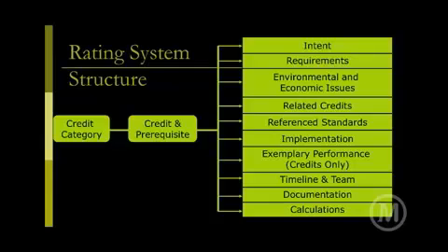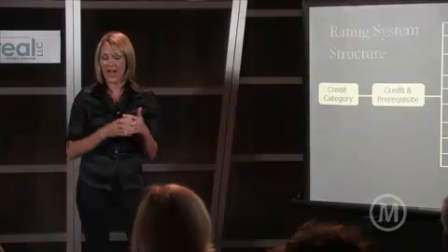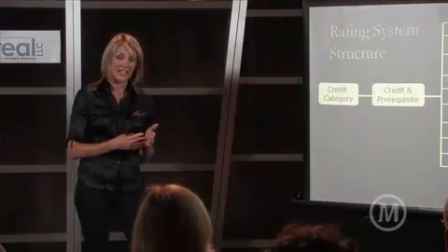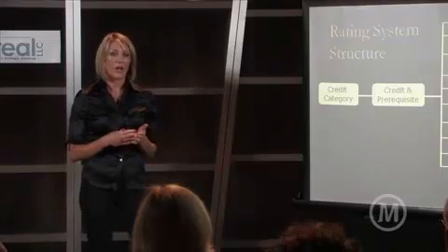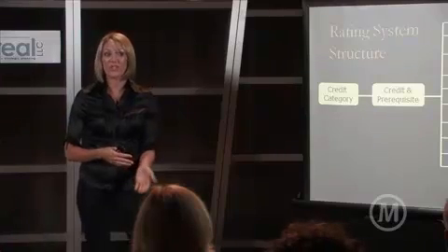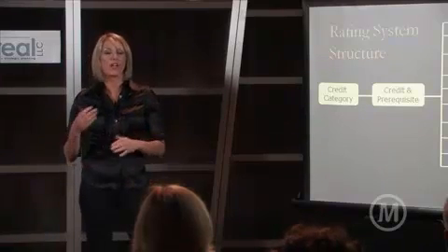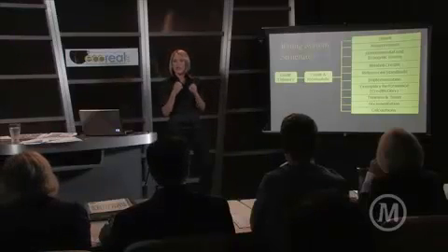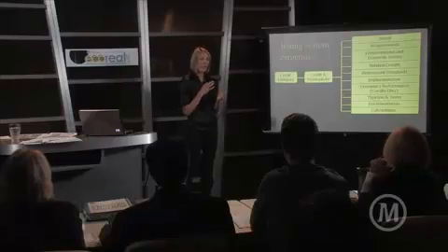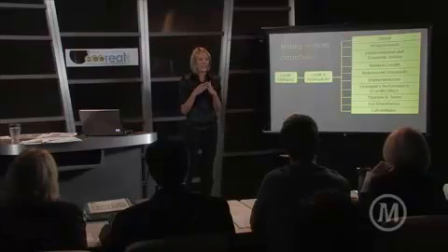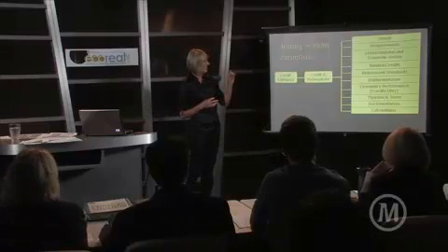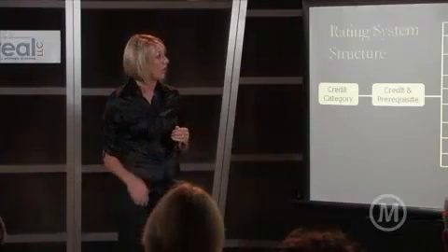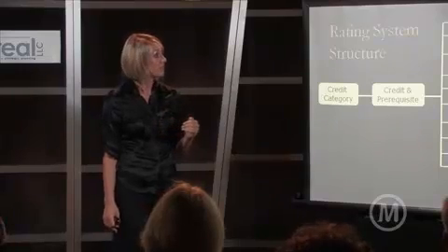Related credits. So here we're talking about synergies, how these interact. Some of them negatively counteract each other, like increased ventilation can require more energy consumption. So all of a sudden you have to think about, well, can we do heat recovery to reduce some of that extra energy load from more ventilation? It just triggers that thought to maybe think about how these two things are interacting with each other. And the reference manual will highlight those. So you start in your conversation. So it's a great tool for the design process.